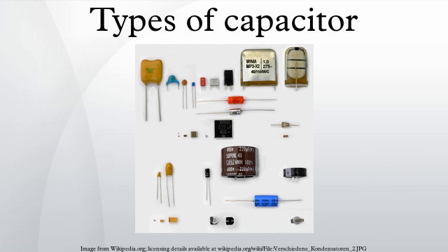Electrolytic capacitors. Electrolytic capacitors have a metallic anode covered with an oxidized layer used as dielectric. The second electrode is a non-solid or solid electrolyte. Electrolytic capacitors are polarized. Three families are available, categorized according to their dielectric: aluminum electrolytic capacitors with aluminum oxide as dielectric, tantalum electrolytic capacitors with tantalum pentoxide as dielectric, and niobium electrolytic capacitors with niobium pentoxide as dielectric. The anode is highly roughened to increase the surface area.